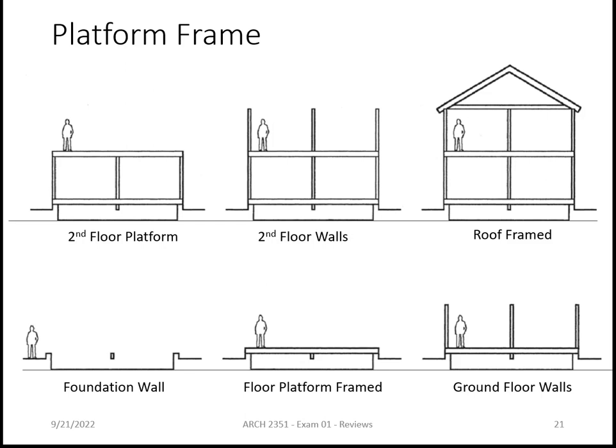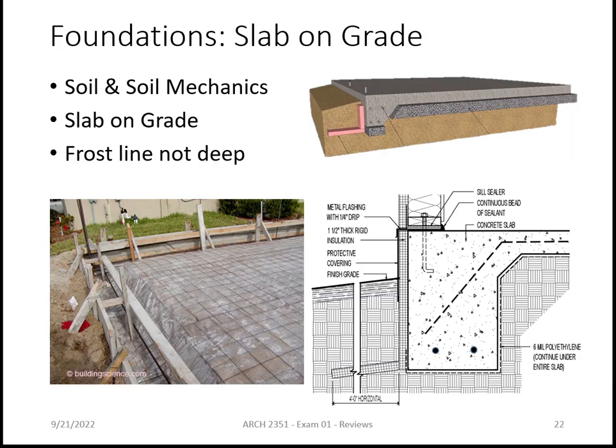Okay, so the first step is a foundation, and there are three types of foundation. Slab on grade, with a continuous footing. What you need to know here are the major components. This is the footing, and there's the slab. They may be separate from each other. There may be a joint right here. Doesn't matter. It's still slab, still footing.